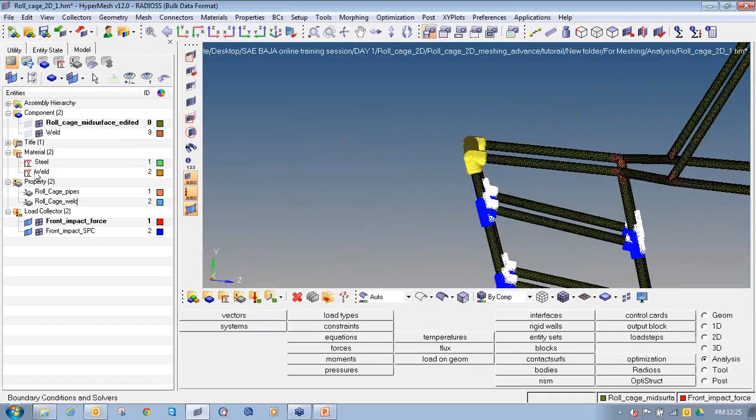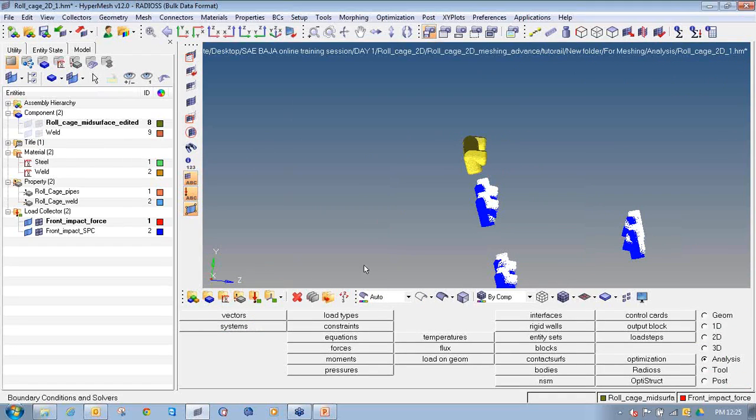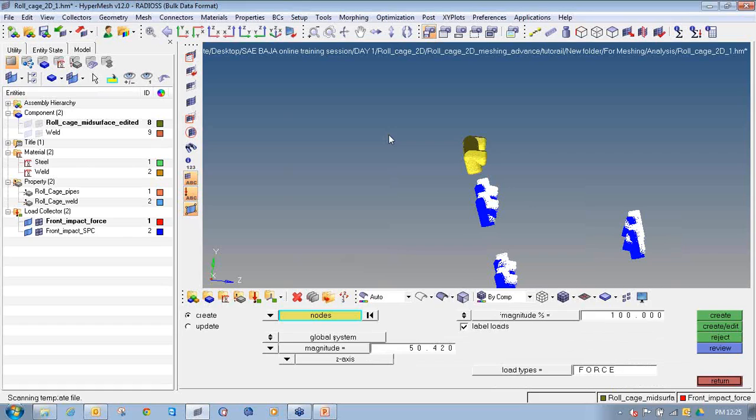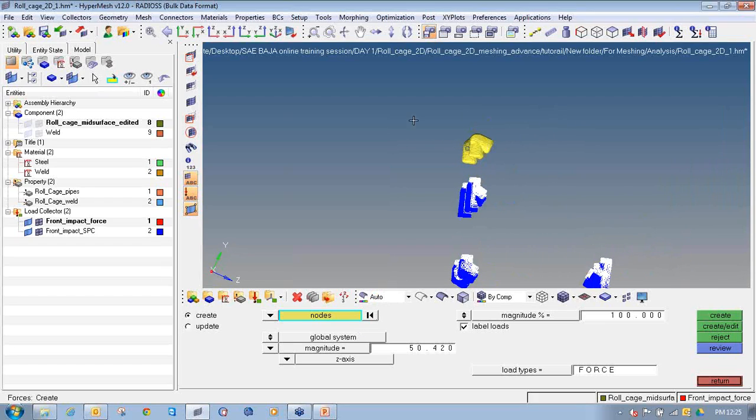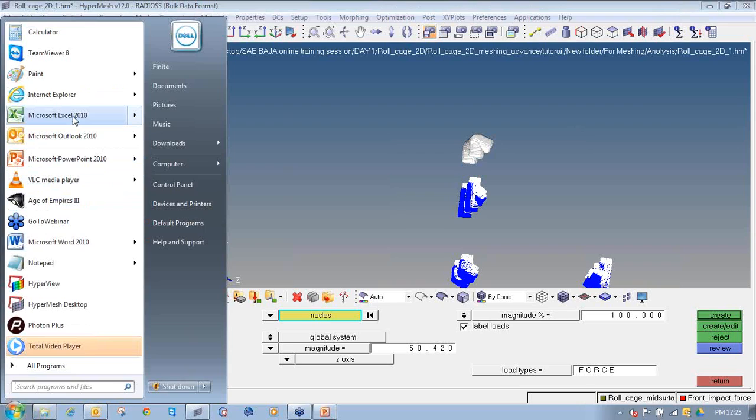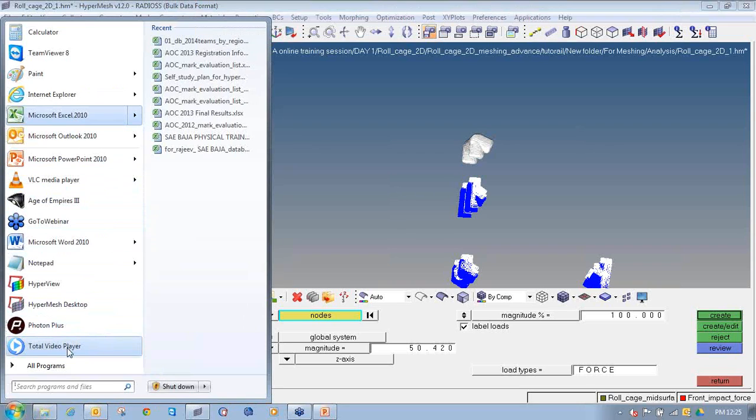Then click return. With these two meshing off, go to analysis, forces, select all the nodes which you have created. It will show you that 3586 nodes have been added. So it contains 3586 nodes, as you can see. Once you select, don't move the model, it will be highlighted only. So 3586. Let's suppose I apply a force of 1000 Newton.